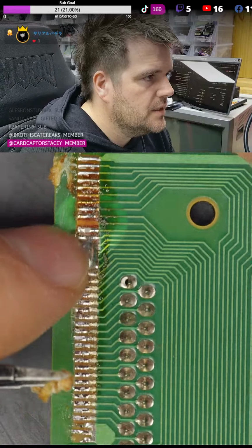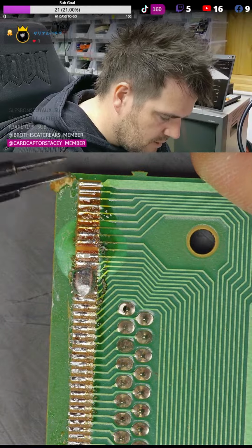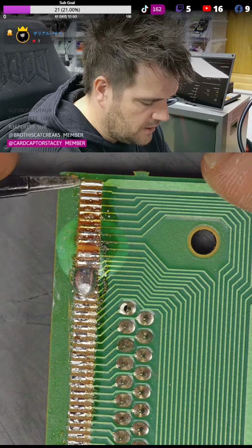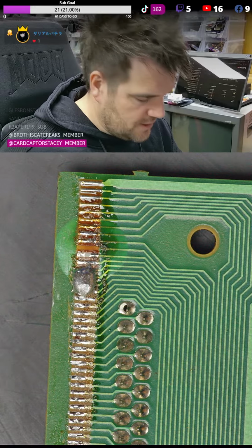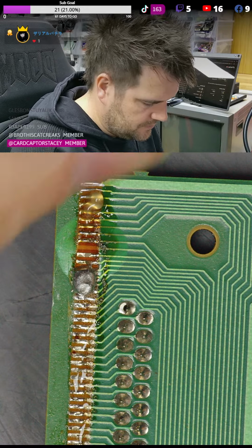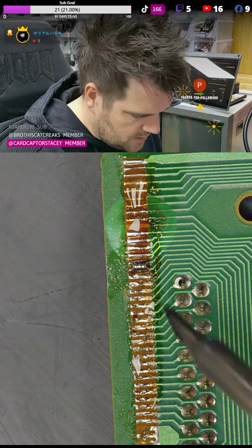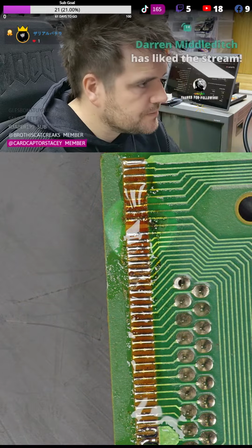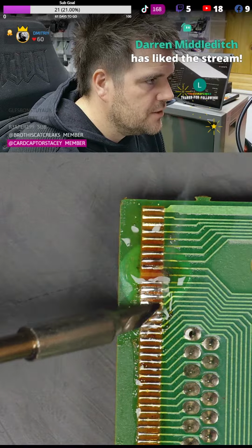Yeah, you can see as well, even that one's come off, so these are quite weak. We'll obviously restore them when we put the connector on. And they shouldn't really rip that easy. That seems to be quite easy that it's ripped, but it's no problem to fix that. Let's first clear off the excess solder. I will probably hot air this connector on. I'll see, because we have the cartridge connector the other side.